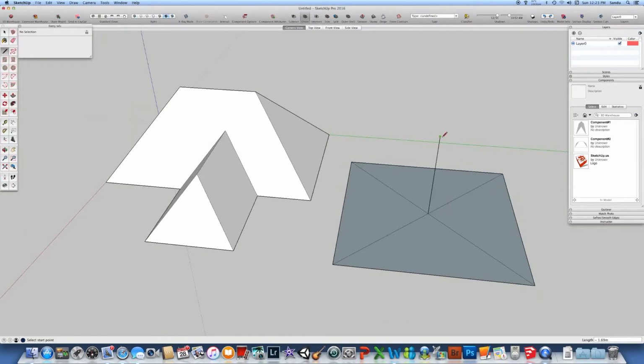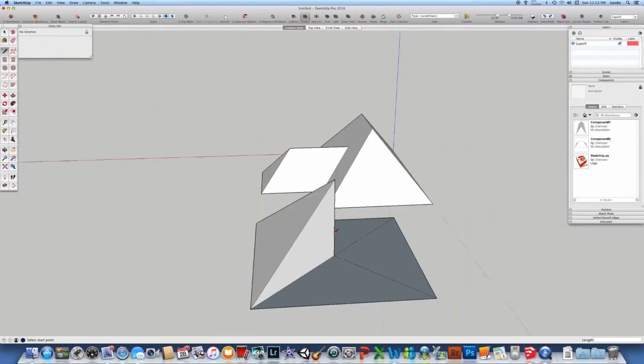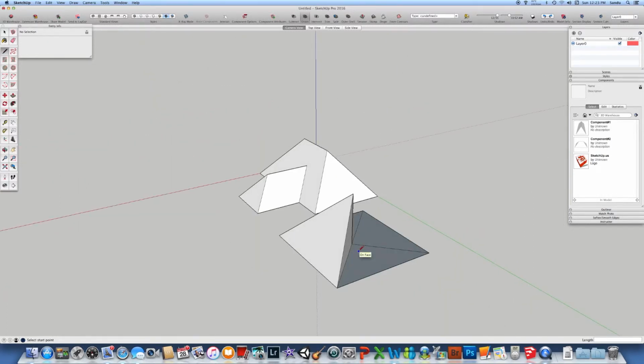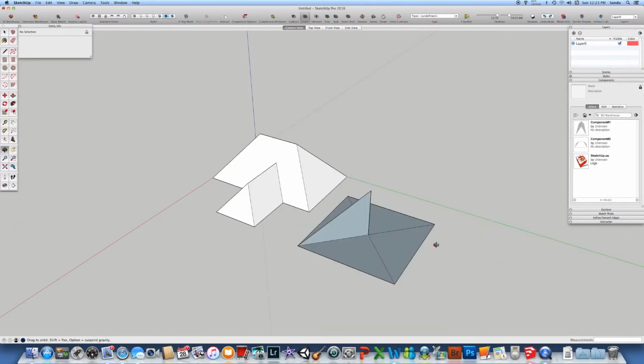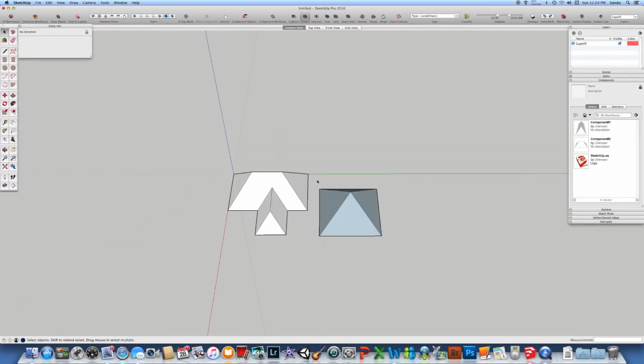You just build another line, and instead of building the faces like this, which is going to create other faces inside, you can use a trick in this way. You basically just try to move up that line. So basically you select this line which is in the middle and move it up. You click on M and you just move it. Make sure always the faces are aligned.